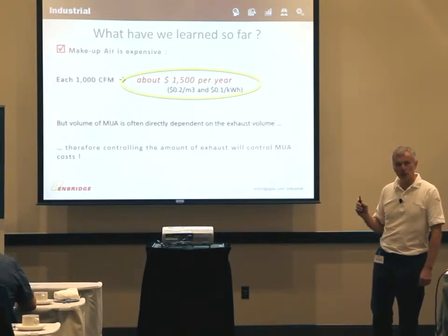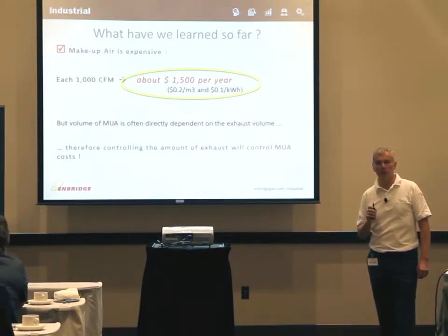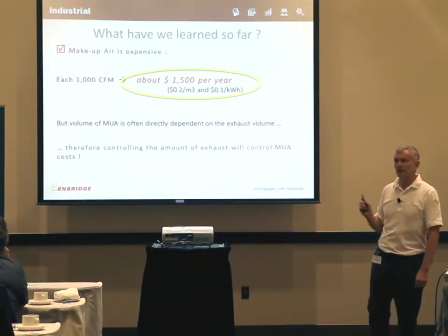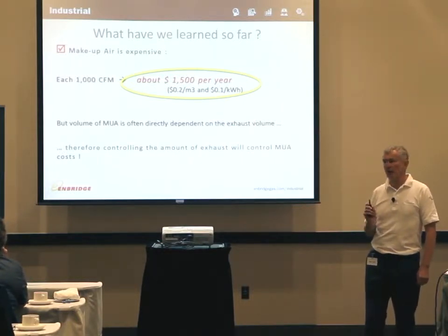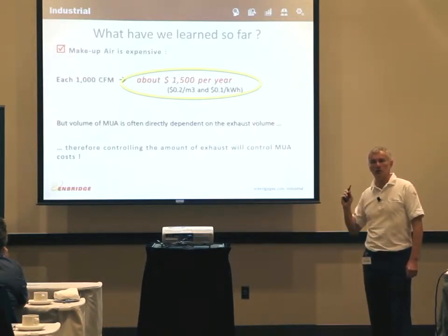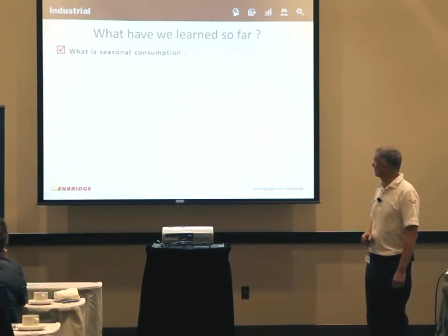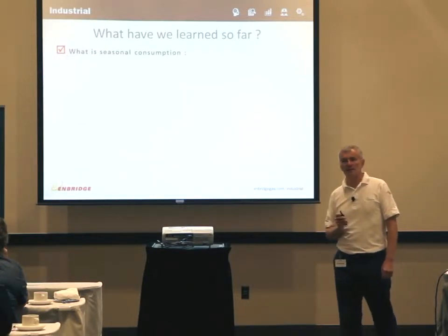So controlling that exhaust volume will control makeup air costs. It's not always obvious to think in those terms, but this is exactly what it is. A well-balanced facility will need about the same amount of makeup air as it has exhaust. We also learned about seasonal consumption.